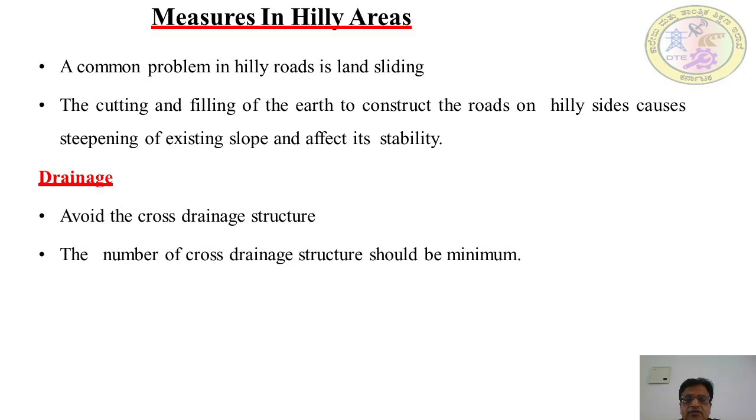The cutting and filling of earth to construct the road on a hilly area causes steepening of the existing slope and affects the stability. Whenever we take the alignment of the highway either in cutting or in an embankment, obviously the stability of the adjoining structure is going to be disturbed. So you need to take that factor into consideration.